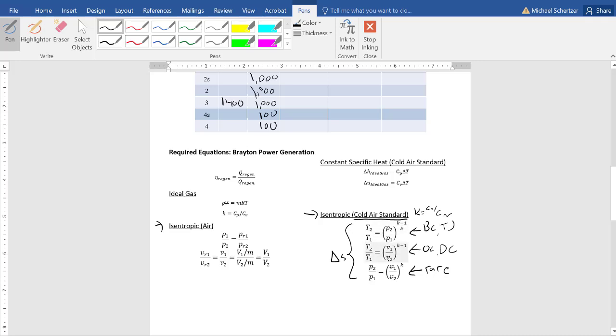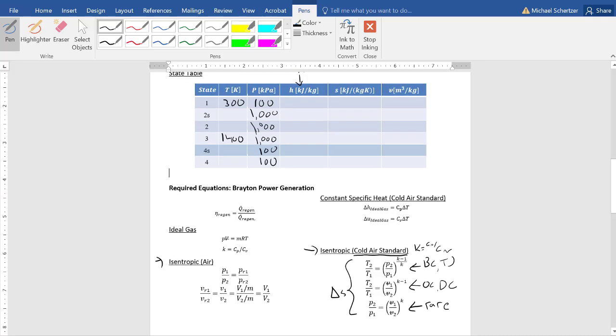And that's because in the Otto cycle and diesel cycle, when the piston is moving up and down, I know about the compression ratio, or maybe the cutoff ratio in a diesel cycle. So the volume ratios in the piston-cylinder assembly are important, right? But volume ratios make less sense when we're talking about open system processes, where we'll normally know the compressor pressure ratio, right? They told us that P2 was 10 times P1. So usually in these open systems, we're going to know these pressure ratios.